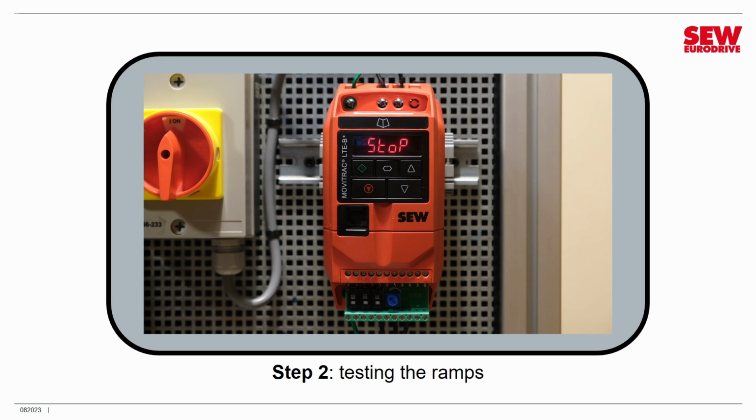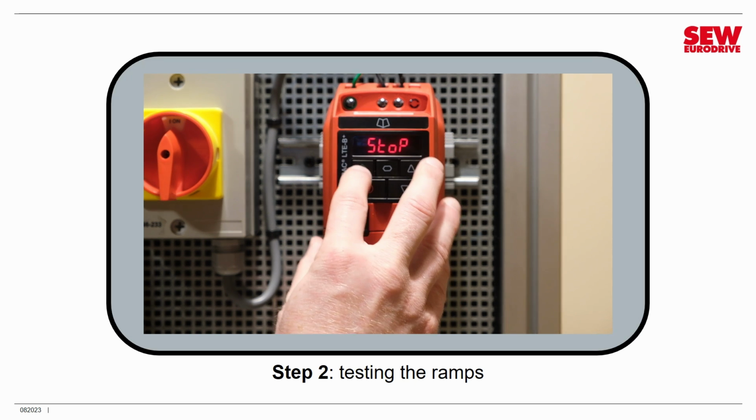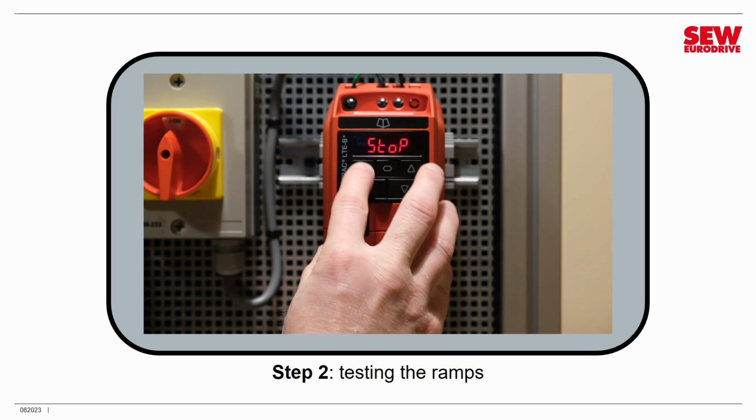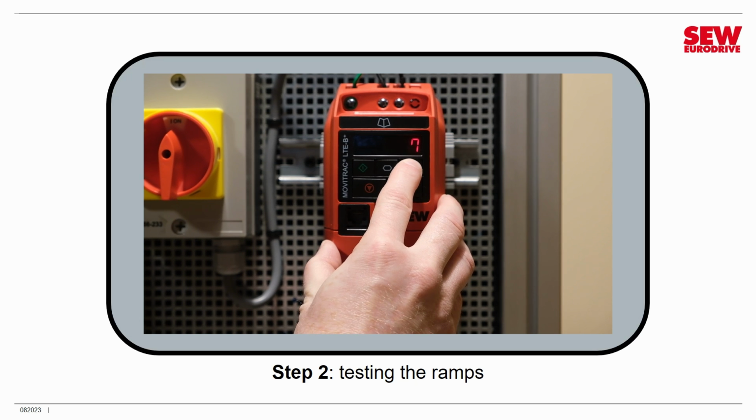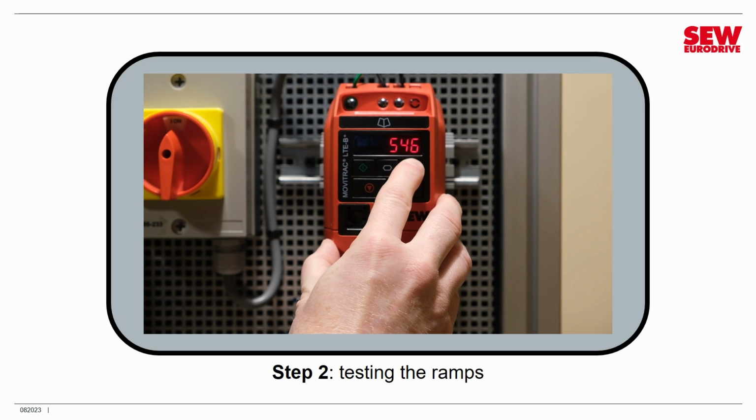So what I'm going to do first of all is get my speed preset. I'm going to turn DI1 on to enable my drive, and then I'm going to press the start button and then use the up and down buttons to get that speed exactly at 900 RPM. So I'm going to adjust my speed here.